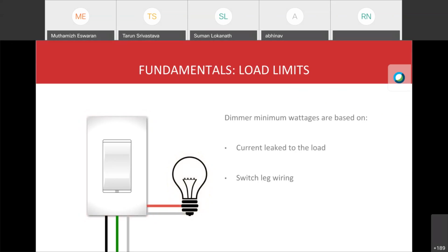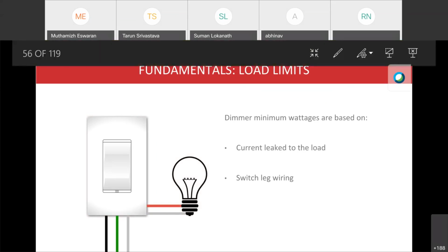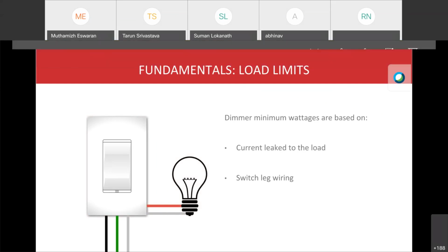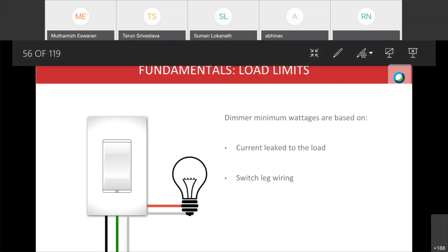On dimming, most dimmers can also do something called a switching leg, which is very similar to a normal manual switch, where it connects only the phase and switches only the phase, so we can work without a neutral. In this kind of case, you need to consider a lower wattage than what you would connect with a neutral, because your leakage will be more.